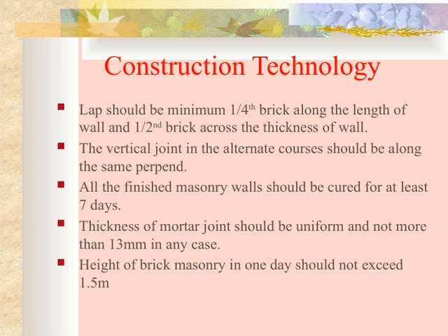The mortar joints should be uniform in thickness, and this thickness should not exceed 13 millimeters in any case. Consistent joints contribute to the aesthetic appeal and structural integrity of the wall. Finally, the height of brick masonry constructed in 1 day should not exceed 1.5 meters.